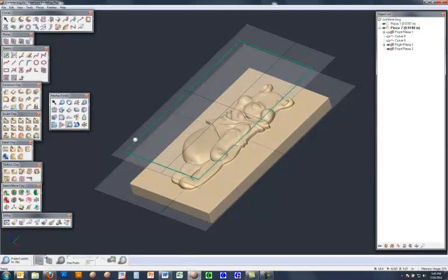The first step is to select that sketch loop. The next step will be to select the limiting plane. And then I can actually change the number of control points here. So I have mine set to 80. And then I'm going to go straight to the end and choose the option to create patches.